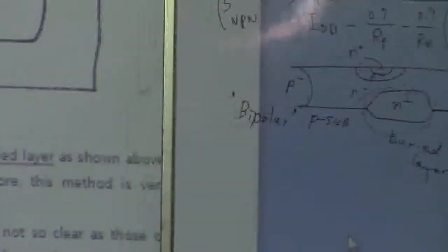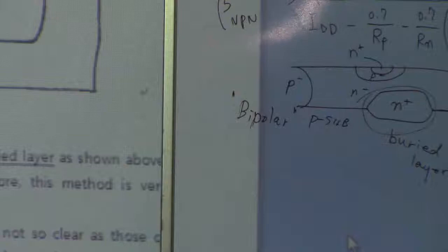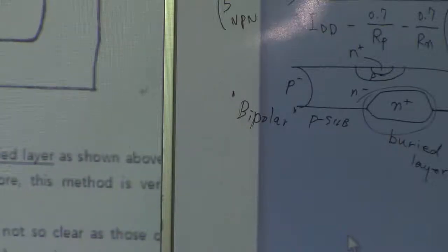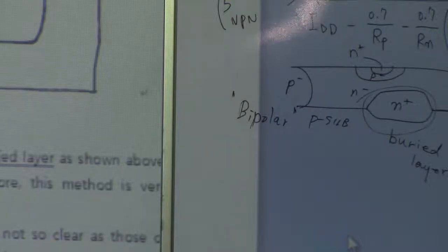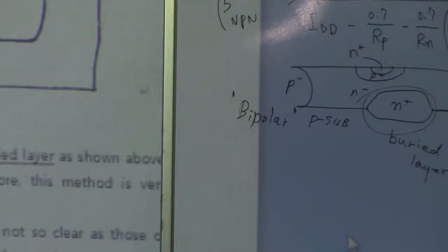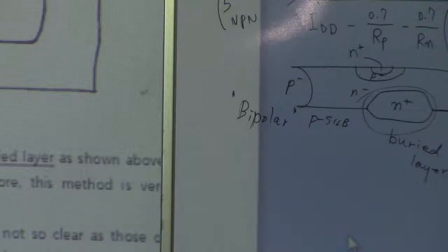And this buried layer part is going to be applied to this CMOS process to make this buried layer, and that buried layer is going to reduce these two resistance values, and that reduction is going to affect the beta value of the lateral transistors, so that the whole thing is going to be helpful to prevent or minimize the latch-up process in CMOS.